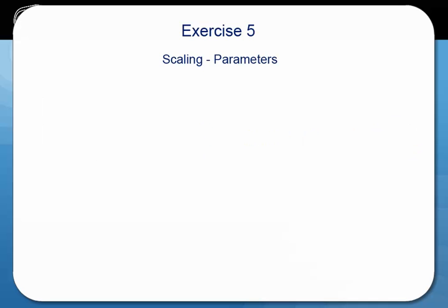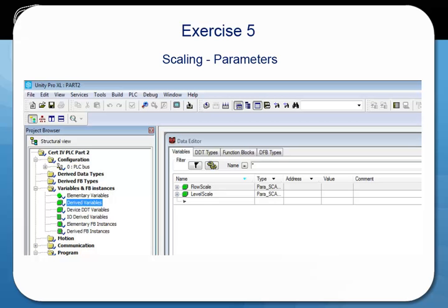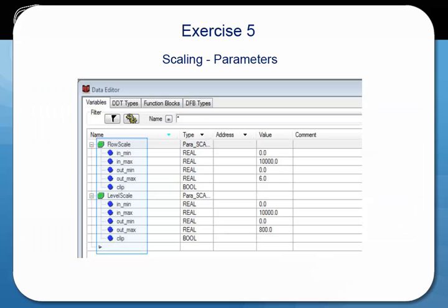The parameters input of the function is a special type of variable that contains subvariables. This particular one has 5 subvariables. The parameter variables are in the derived variable section of the project browser. You will see the variables that are created for this project. Open up these variables by clicking on the plus sign and you will see the subvariables in-min, in-max, out-min, and out-max. You will also notice that we have put values in here already.